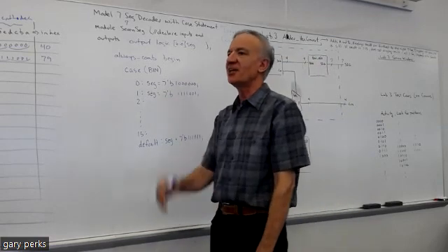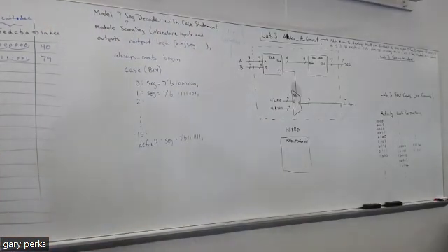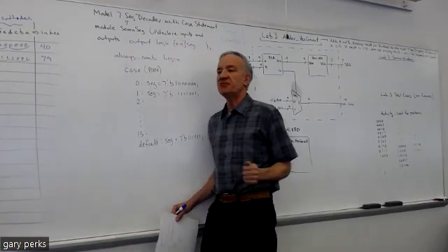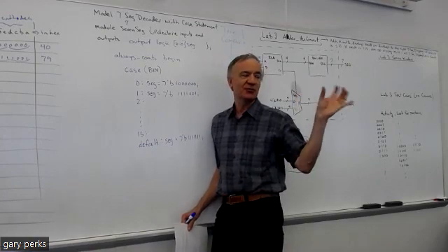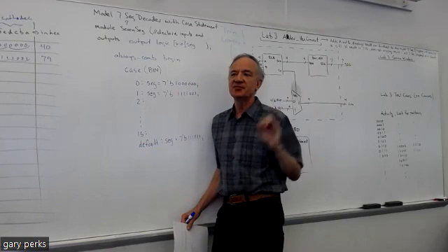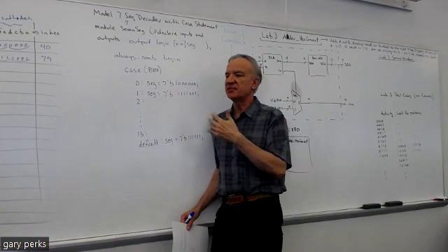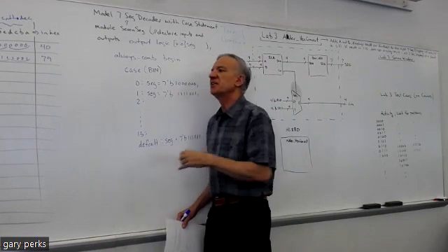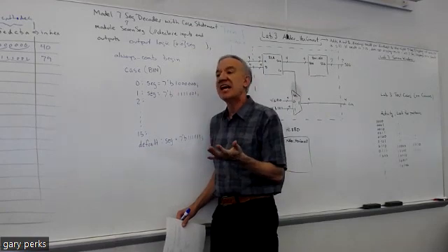No, but actually, I'm glad you asked that because there was something last class that I meant to mention that I didn't, and I wasn't too worried about it because it's going to come up again. In a case statement, if you don't have a default, it's going to create a latch. That ugly word we've been saying, if that's in a warning, treat it like an error. Again, a latch is a memory circuit. We're going to get to it in a couple of weeks. So if you don't have a default, it's going to put what's called an unintended latch into your circuit.